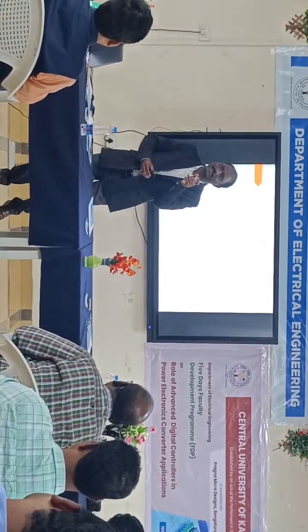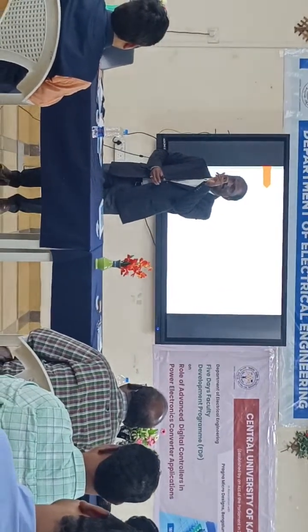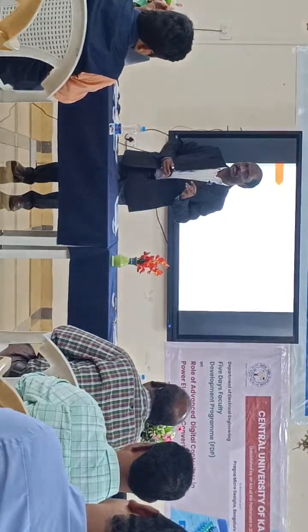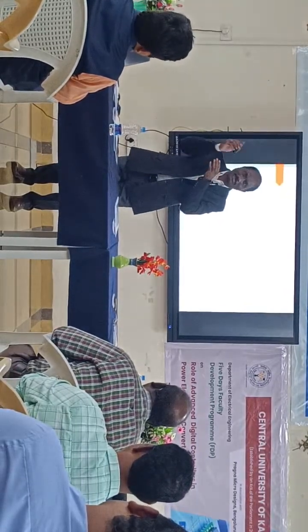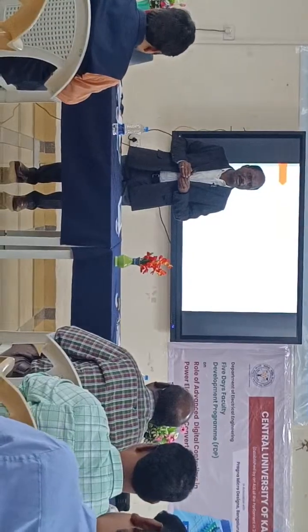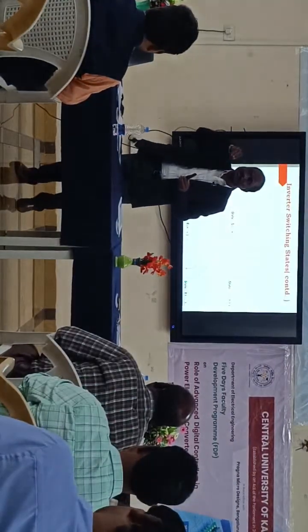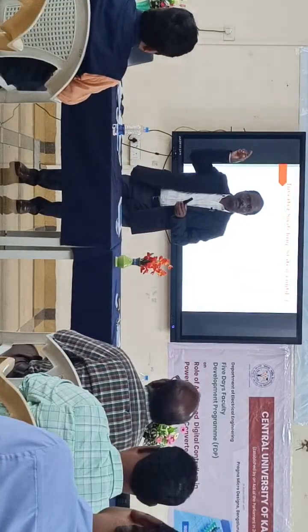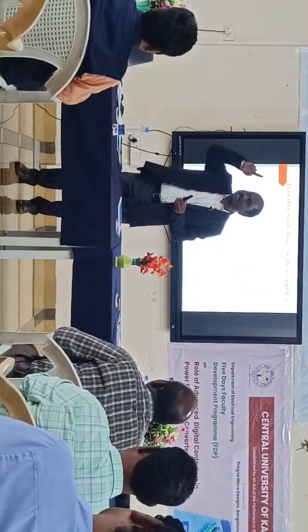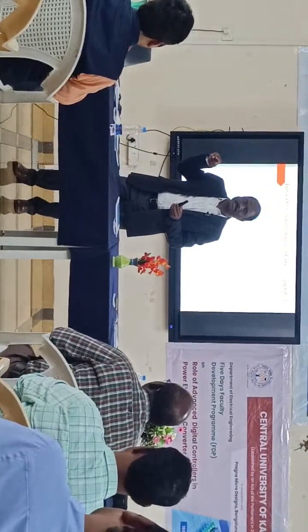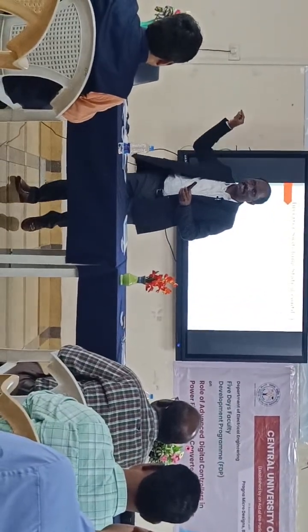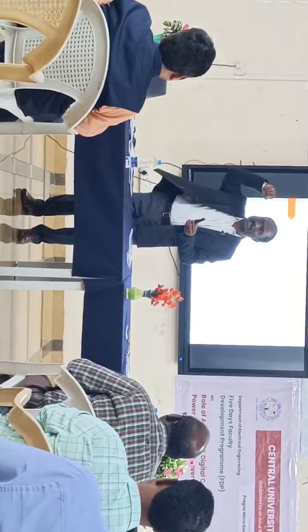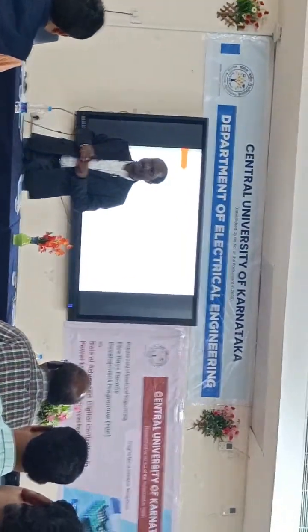0 plus VDC e power j2 pi by 3 plus 0. What is that? VDC at an angle of 120. So your reference vector is at VDC at an angle of 120 when we are operating some all plus or minus 0. When plus minus minus we are going to get VDC at an angle of 120 like that. Plus minus minus is VDC at an angle of 0. Minus plus minus means VDC at an angle of 120.